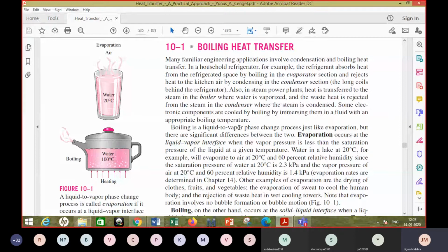because there is a boiling involved where the change of liquid phase to vapor phase is taking place, and the opposite for the condensation. And so the mechanism is, though there is a bulk motion of the fluid, so we can always call it convective heat transfer, but boiling heat transfer and condensation heat transfer, they are a bit different from the sensible, only sensible heat transfer that is taking place in regular convective heat transfer phenomena.